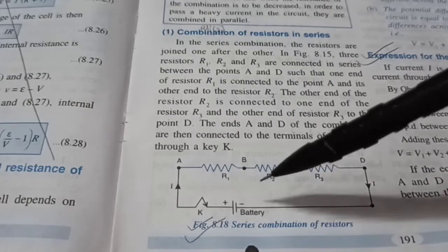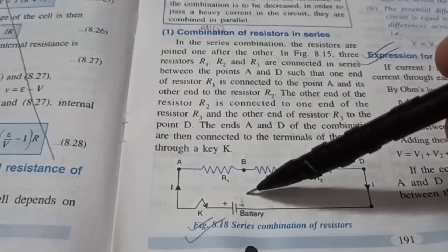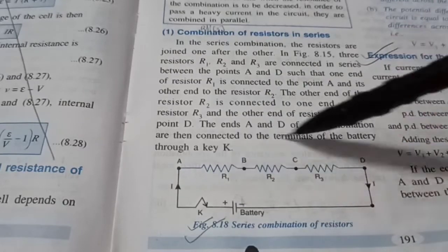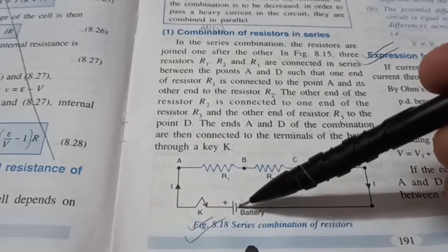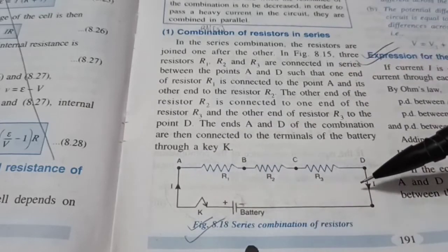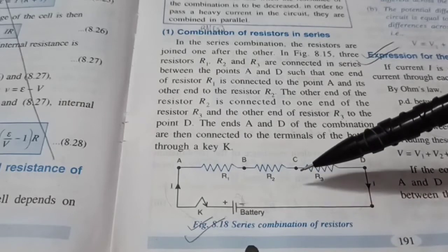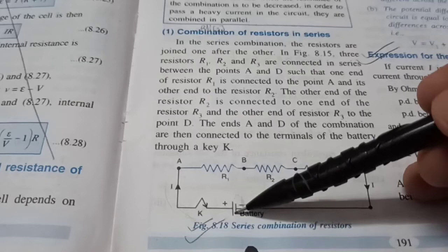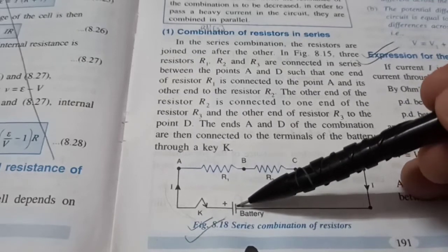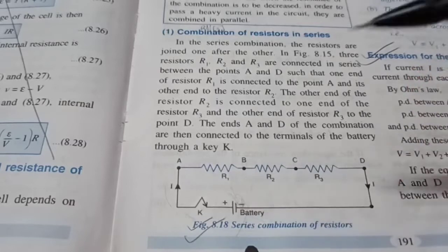By the way, there will be some internal resistance, small r, also, let's say 0.2 ohm. So we might have to calculate that as well. So it will become 7.2 ohm, the total resistance. Even this is in series with the rest of them. So in a numerical, which we'll do next week, if there is a mention about a potential voltage drop or internal resistance, then keep that in mind. But in any numerical, if there is no mention of it, then we can just ignore the internal resistance.